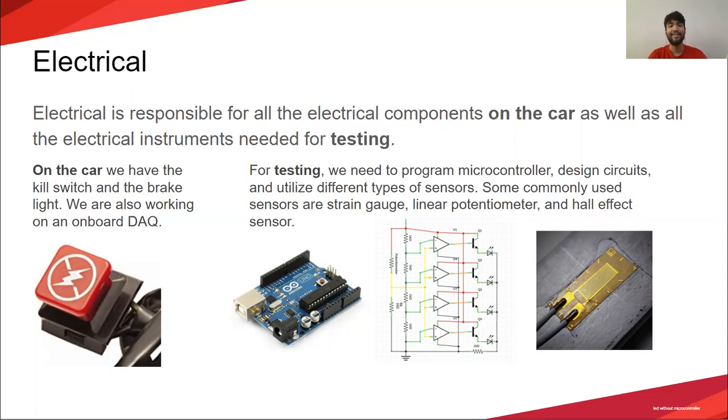A strain gauge, for example, needs a Wheatstone bridge to give a voltage signal and an instrumentation amplifier to amplify that signal. Then, we need a microcontroller to store and collect that data in a way that can be analyzed in the future. The last step is to move everything you make into a sturdy platform so that your device won't break during the test.